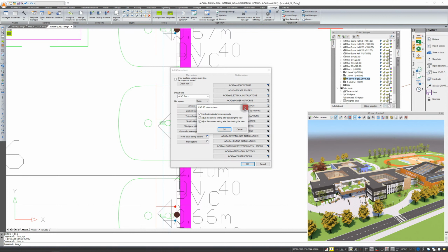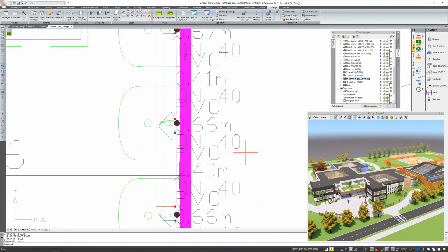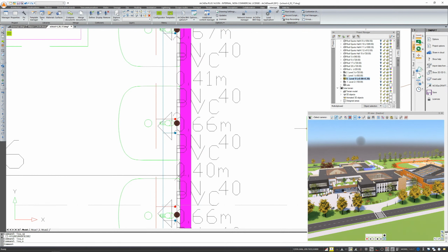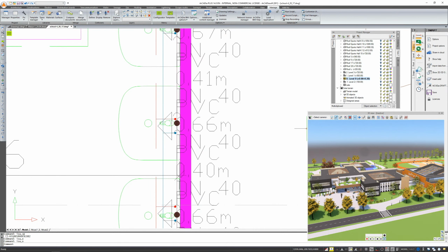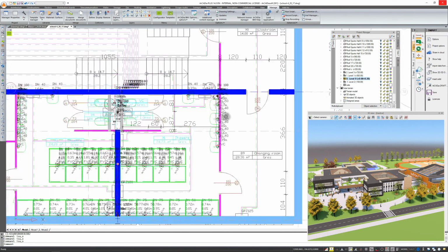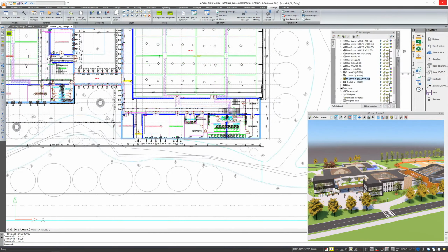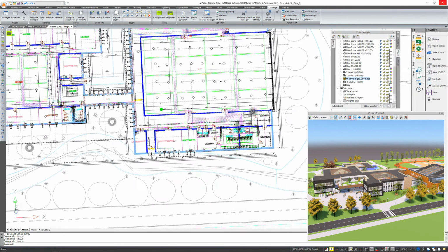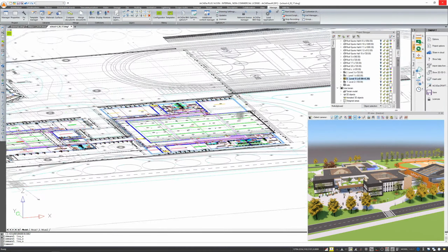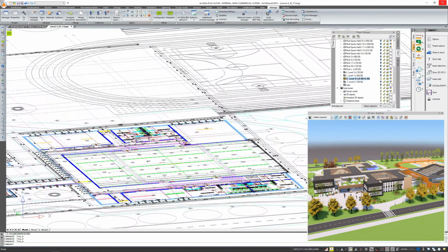And when you hand over the project to someone who does not have ArCADia and has a different CAD program, it would be good for him to receive information about the entire model, including the heights, so that he could read it by himself. He will not have this 3D view, as I have in the preview here, so he will only have what is in the drawing. And here, please note that if this 3D CAD view does not exist, it will only have a flat drawing, in which there will be a wall, but a block that will be drawn with one line. There will simply be no information about the element.